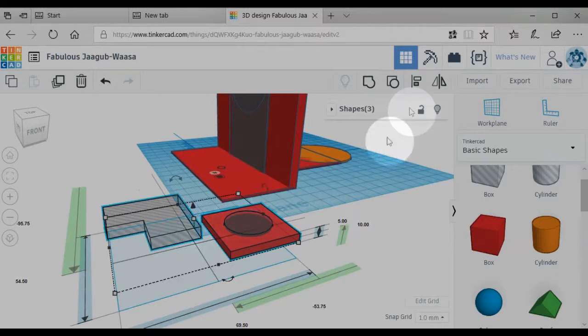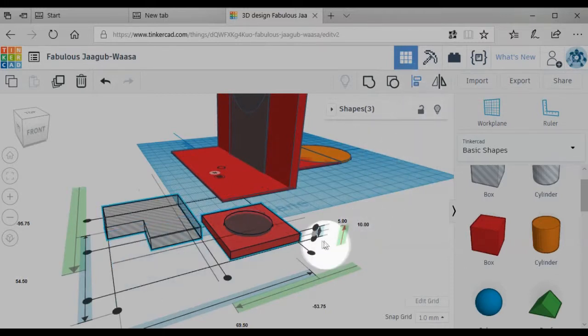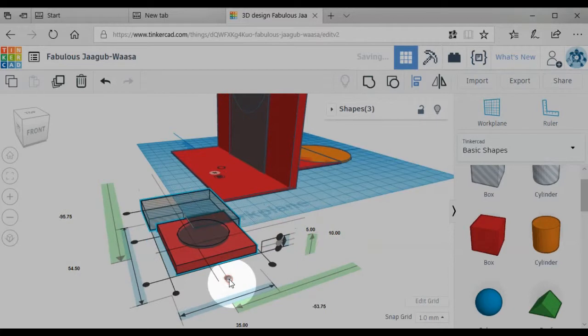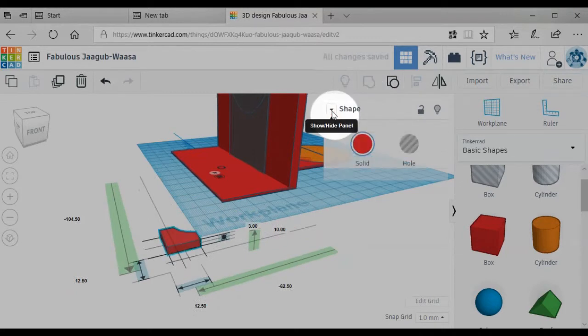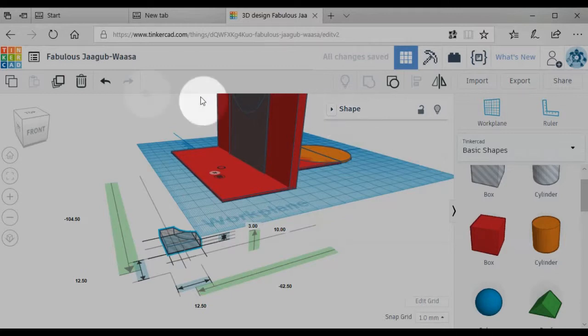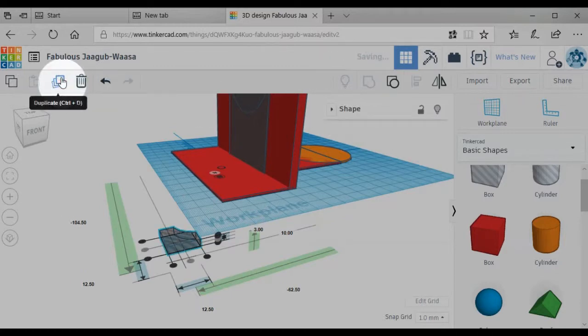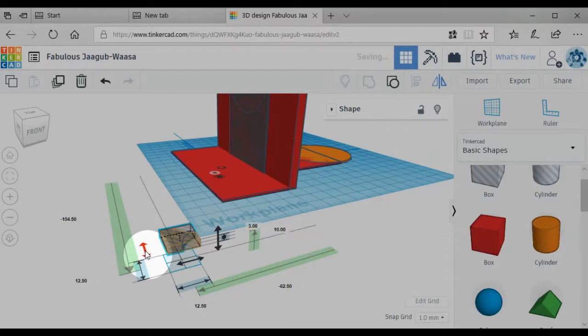Activate the Align tool, and use the 3 center pins to center all 3 pieces. Using Group on the 3 selected pieces creates an object which can now be assigned the hole color. To make a cornering hole for the other side, use Duplicate, and then activate the Flip tool on the right end of the toolbar. This makes 3 bold arrows appear around the object. Use the arrow that points along the y-axis to make the duplicate cornering hole work on the far corner.